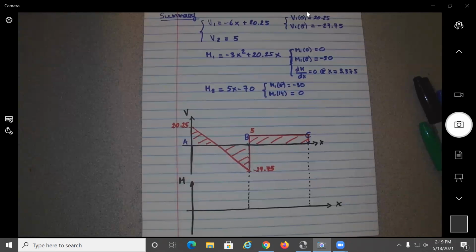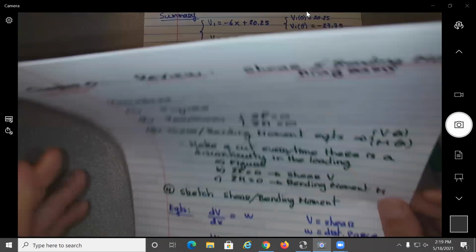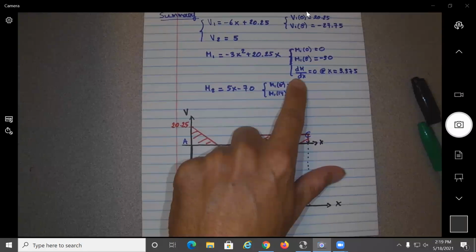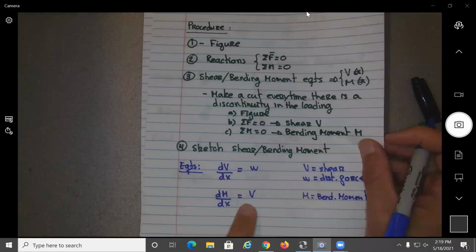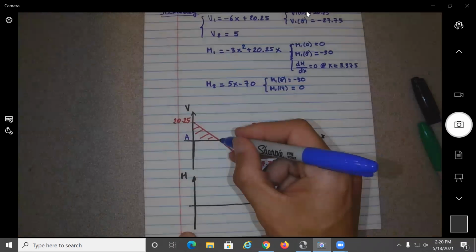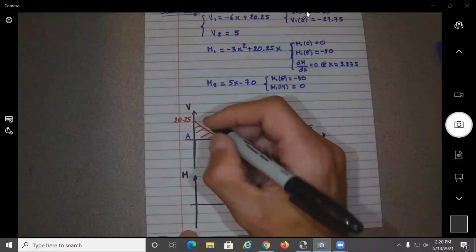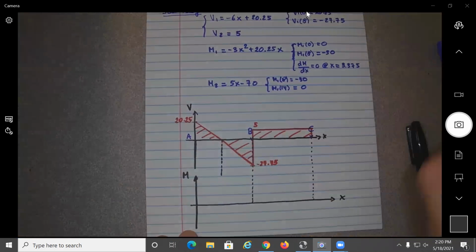Okay. Now, because I did not select it to use the equation, what is this point? What should be this point here? How did we find the maximum of this one here? We did dM/dx equal to 0, no? Yeah. But also, what do we know? dM/dx equal to V. So that means V equal to 0, no? When will V be equal to 0? At this value here, no? So really the maximum of this equation will be located at the same point of intersection here.